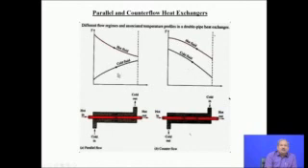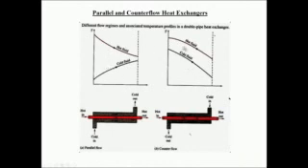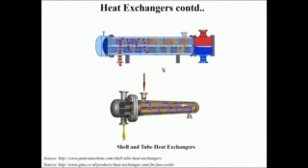So, we will see how to calculate the effective delta T for the case of parallel and counter flow, and whether it is going to be some sort of an arithmetic average, or some other type of average which would give the effective delta T between the hot and the cold fluid for these two situations. So, we will look into that as well.